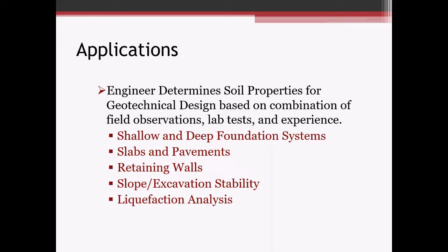Because we can't physically see all the subsurface conditions that exist below a project, we often rely on a combination of field observations as well as lab testing at select locations across the site, along with experience, to evaluate the soil parameters that go into the geotechnical design.